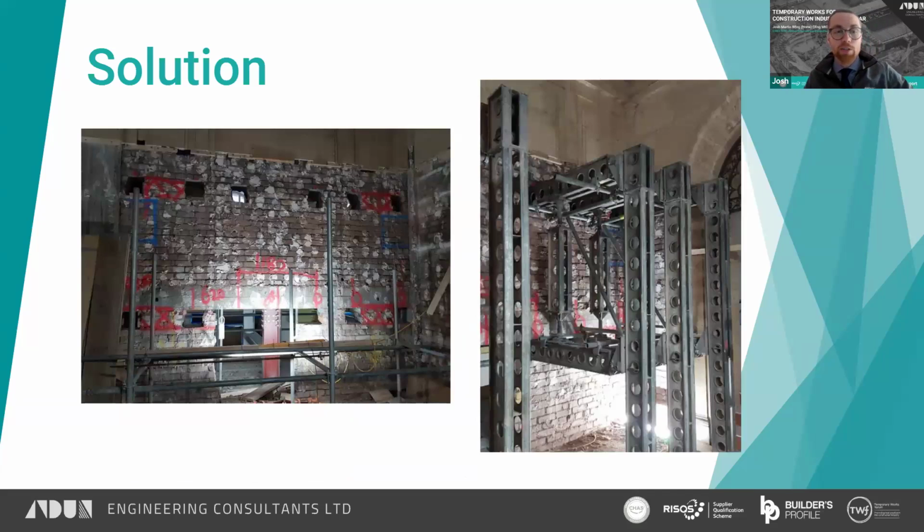And here we've got the solution in reality. So you can see there we've got a number of holes in the wall where we fit the needles, and it's important to have that back prop at the back that loads the floor from the propping self-weight. That enables the thing to be built, and when it starts taking load, then the load is transferred into the wall where the needles are.